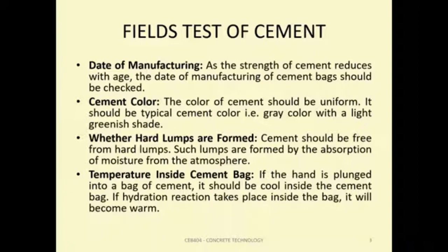The next one is to check whether hard lumps have formed inside the cement. The cement should be free from hard lumps, because lumps are formed by the absorption of moisture from the atmosphere. Then, check the temperature inside the cement bag. If we insert a hand into the bag of cement, it should be cool, because if hydration takes place inside the bag, it will be warm.